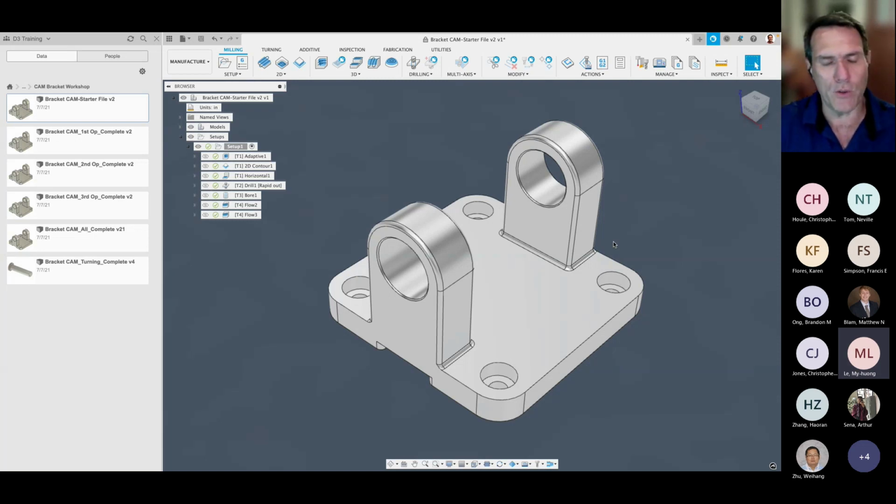The other thing is we're going to be using a tool with a V-shaped tip, or a conical tip is honestly what it is, to be able to cut this chamfer. So we can't just have the tip of it right on that edge, or else it'll mess up the tool and mess up the edge. So we're going to have to offset things and drop things down to add a feature that really isn't even in the design file. So there's no chamfer on our CAD file, but a good machinist is going to want to break those edges to keep a good quality part.